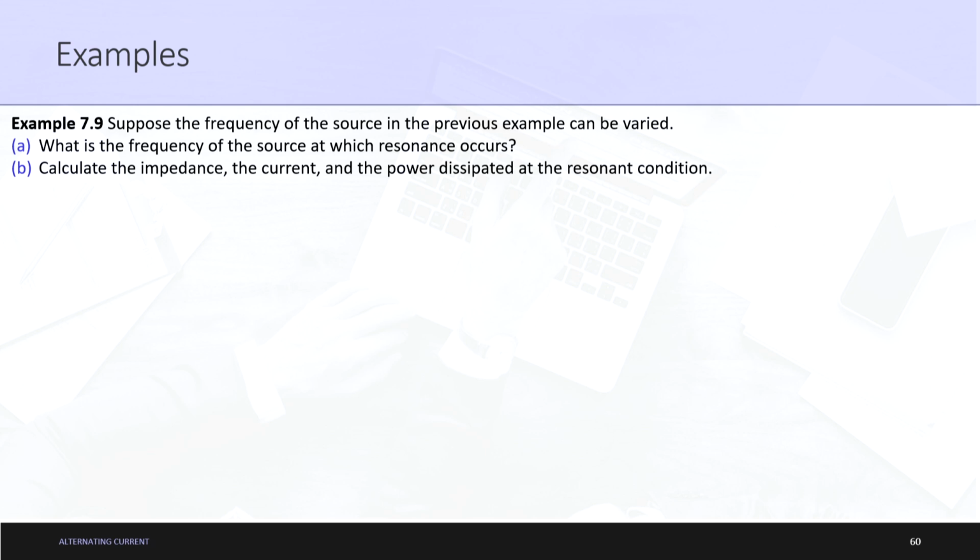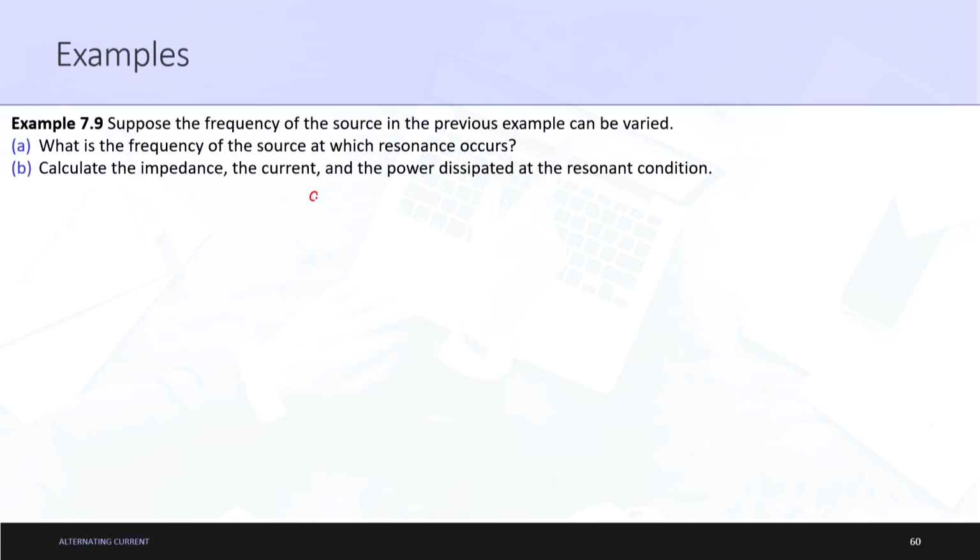If you go back to the concept of resonance, we actually calculated a formula so that we can calculate the value of the resonant frequency. That formula was simple. We denoted it as omega naught, which is nothing but equal to 1 upon root LC. You know the value of L, you know the value of C, just calculate it directly, you will get the answer as nothing but equal to 222.1 radians per second. Okay. So I hope this concept is clear till this point.